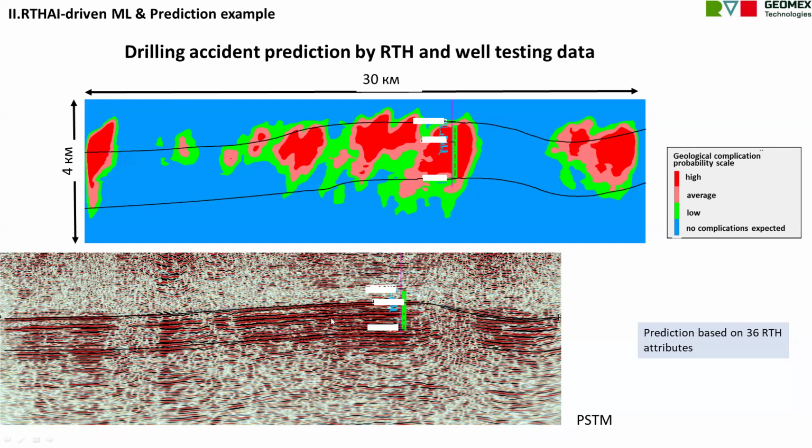By accident, you mean lost circulation? For drilling, during the drilling, only during the drilling. Are you talking about lost circulation? I mean, when you drill a formation that is heavily fractured, the drilling fluid gets lost into the formation, and the loss can be very severe.